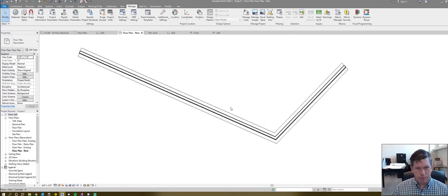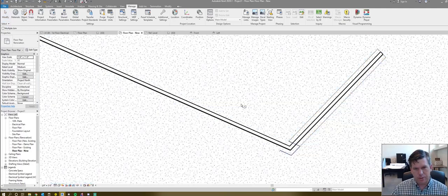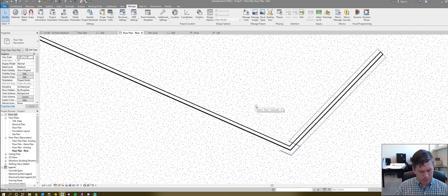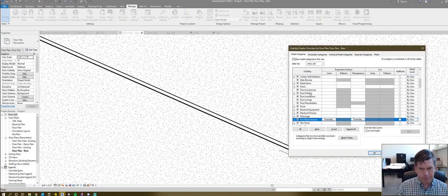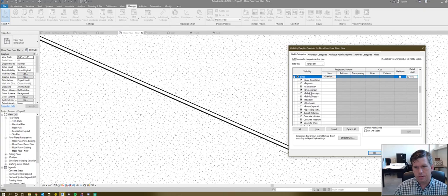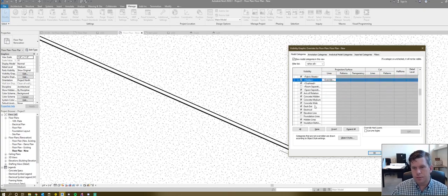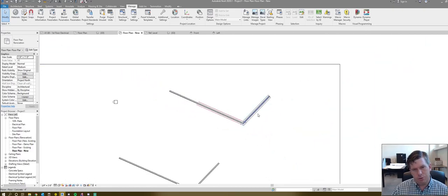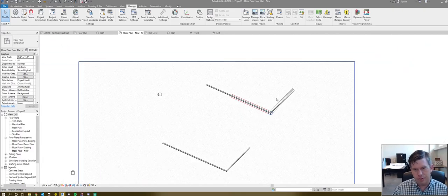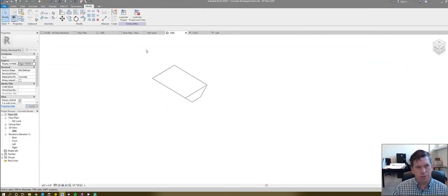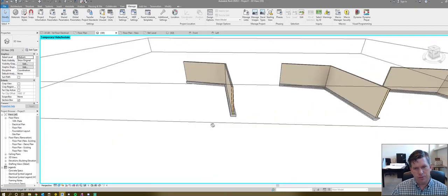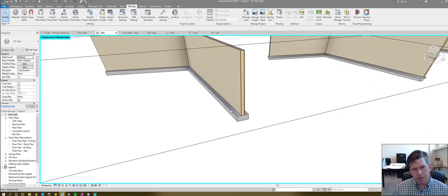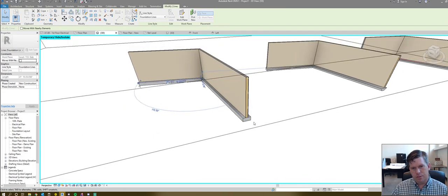Okay, so once this gets joined to my slab, you can see that it disappears. Now if I leave those on, foundation lines, we'll always have these lines sitting in our floor plan, and we don't want that. So this makes it very easy to work in one view and turn those off in another view. All right, so I've got my model lines, and I've got my